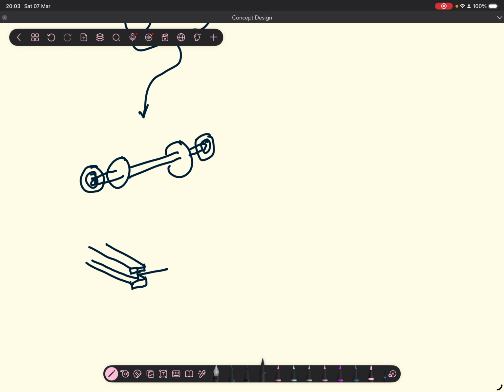So this web over here is very, very thin. So if I draw it like that, you can see it's pretty thin, and my bearing is going to be pretty thick compared to the web. So I won't be able to place my bearing inside here comfortably. It's going to be sticking out kind of like that in most cases.